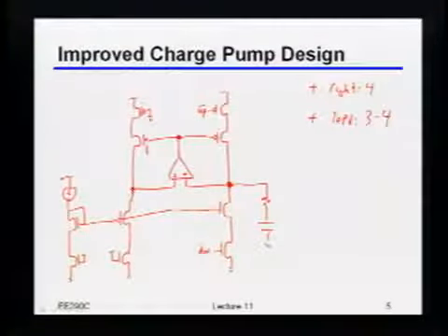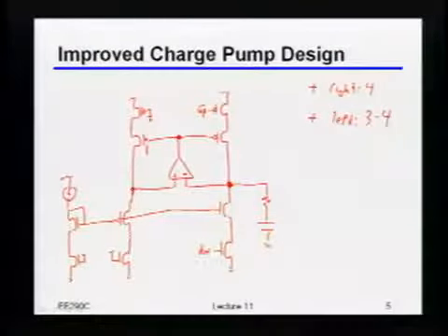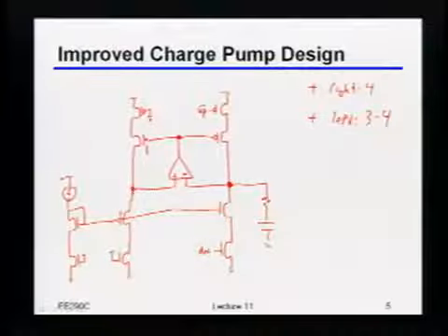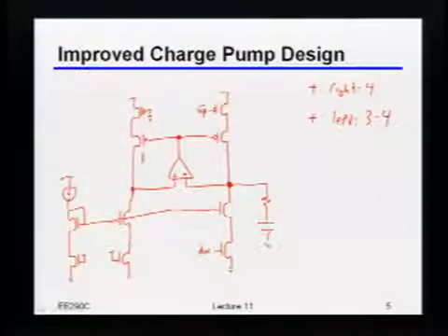It need not be up to the bandwidth of the loop. Well, you have to be a little bit careful, because if it's not up to the bandwidth of the loop, you might start introducing pole-zero doublets and things like that. So it might still be okay, but generally speaking, it doesn't cost you that much to get the bandwidth there, so you'll just do it to make sure that it's behaving the way you'd like it to.